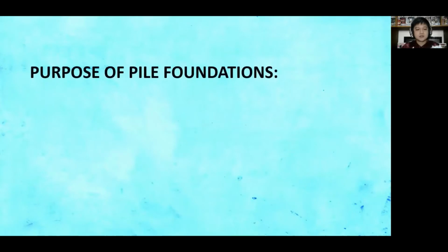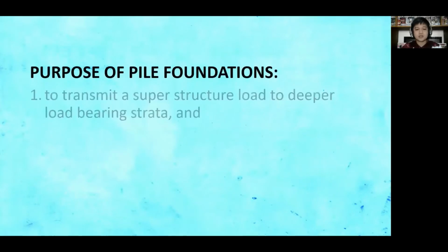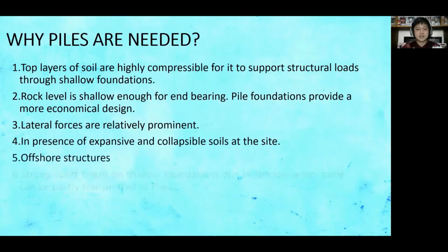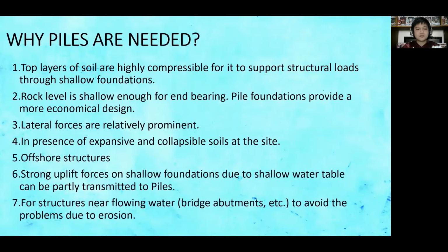What are the two purposes of pile foundations? First is to transmit a superstructure load to deeper load-bearing strata, and second, to withstand lateral, vertical, and uplift loads and to minimize the settlement. So why are piles needed? First, top layers of soil are highly compressible and cannot support structural loads through shallow foundations, especially if the soil carrying capacity cannot sustain the imposed load, which results in settlement.